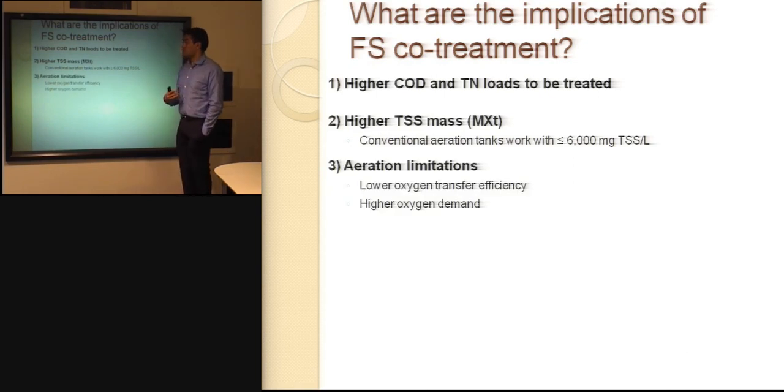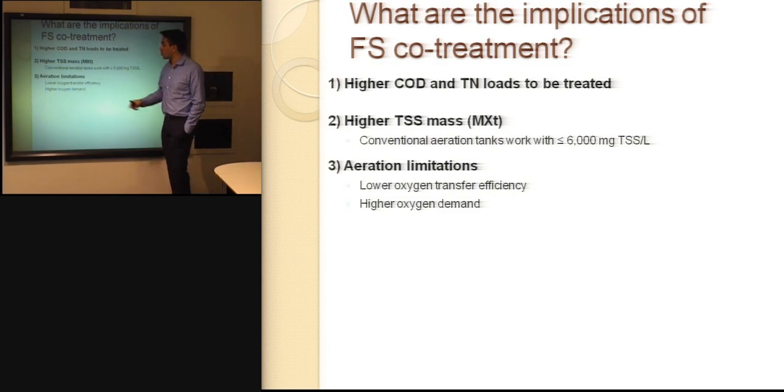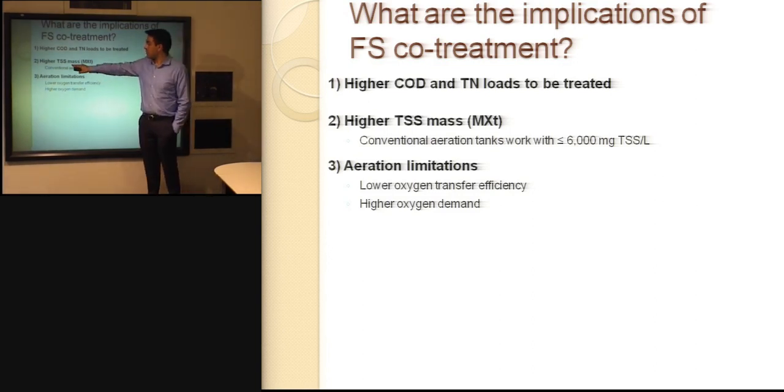This could lead to aeration limitations because most wastewater treatment systems, for example the aerobic treatment systems, will have problems coping with much higher total suspended solids concentrations, which will have a strong impact on the oxygen transfer efficiency.